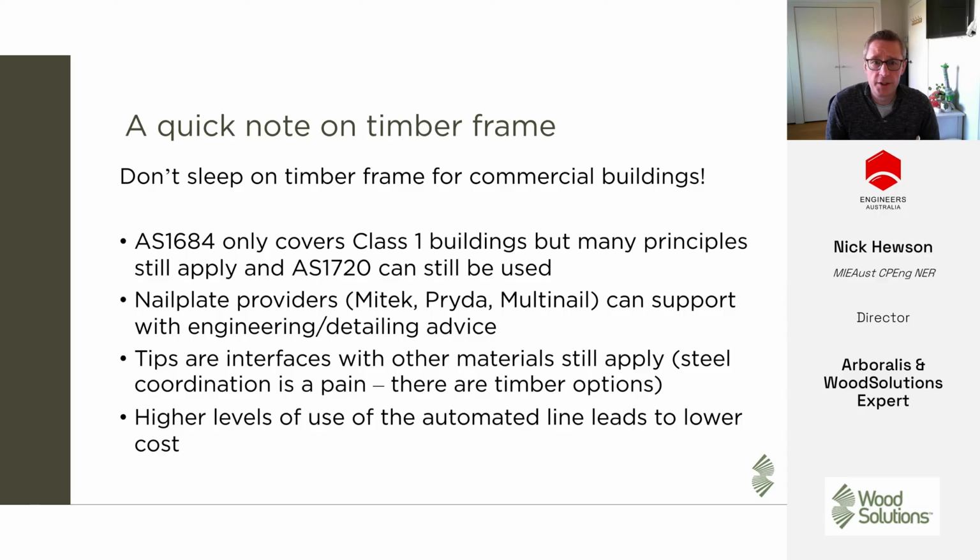And as I said, a quick note on timber frame. This is something that I'm seeing more and more now. AS 1684 covers class 1 buildings, and that's where a lot of our timber frame has been going over the years. But we're seeing more interest in particularly multi-residential, in schools, in aged care, that sort of building. So we see a lot more opportunity there. There are the 3 major nail plate providers, MiTek, Pryda, Multinail, who can definitely support with engineering and advice. Certainly coordinating around other materials is often a real headache there.